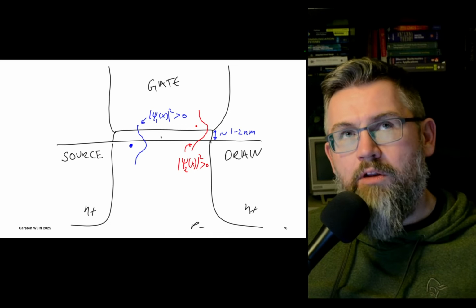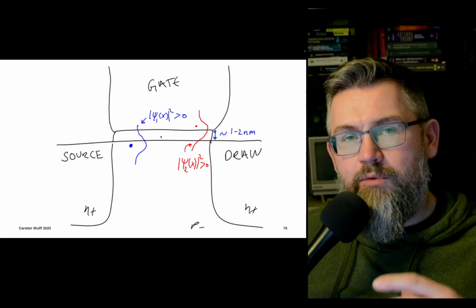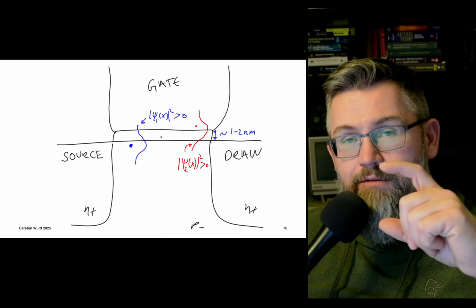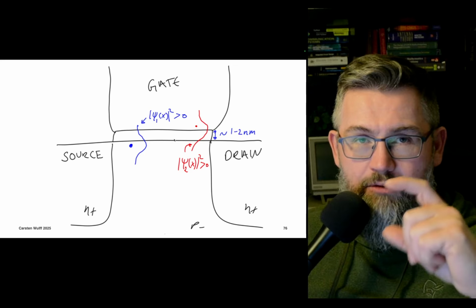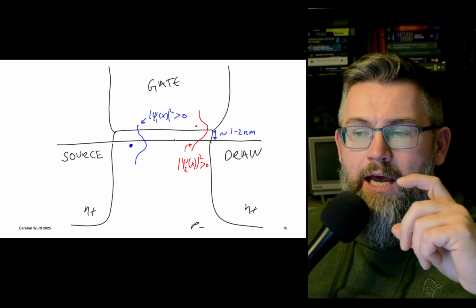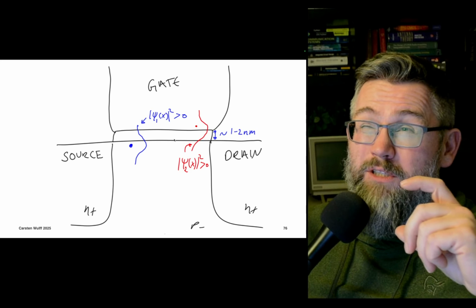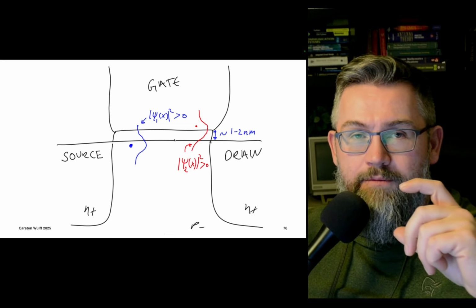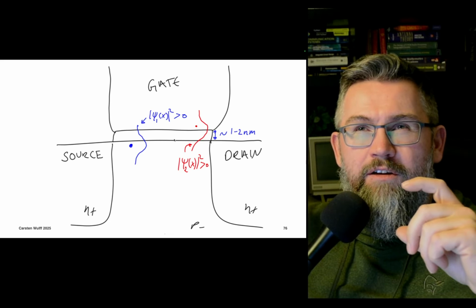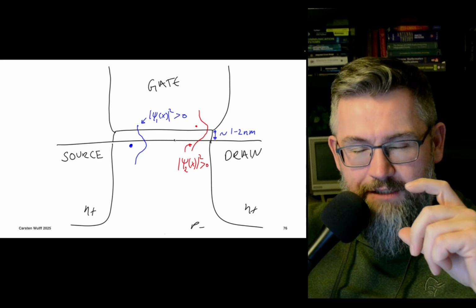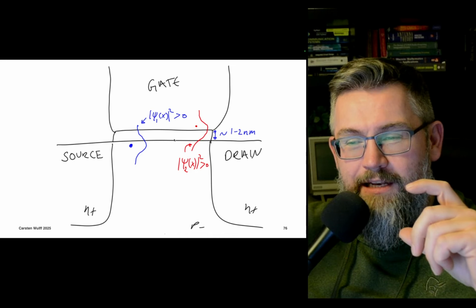That is one of the primary reasons why for transistors these days we have actually increased the thickness of the gate oxide, but using a different type of material, a high-K dielectric, with higher permittivity than silicon dioxide, but effectively the same electrical thickness.